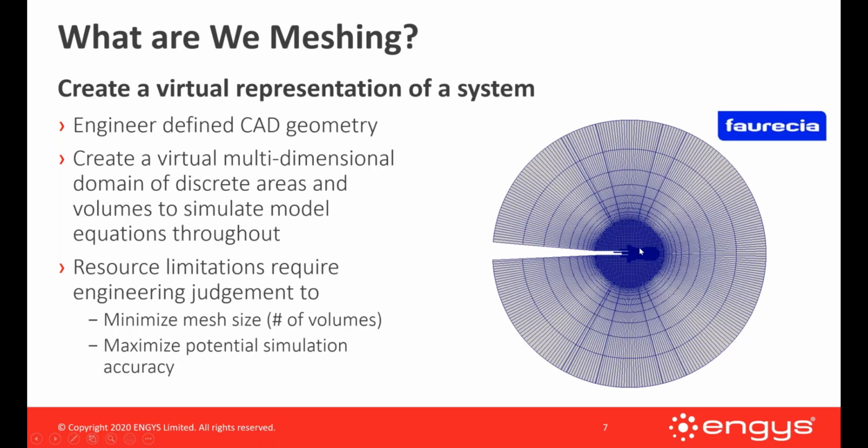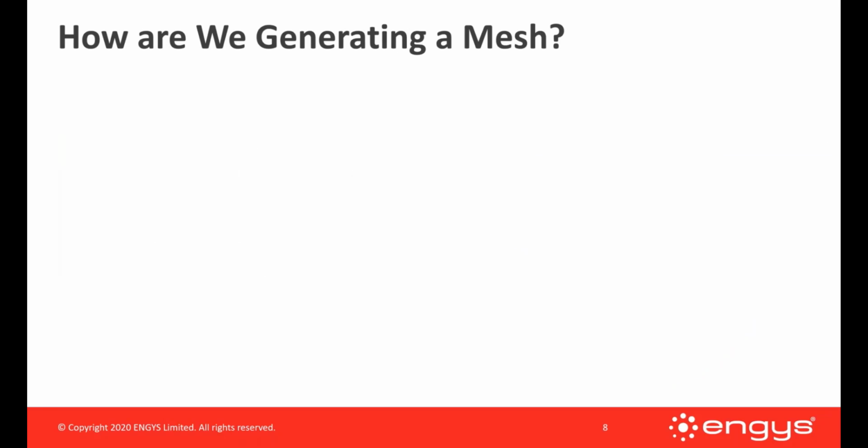And for this particular mesh, there's several different components. So near the muffler, there's extremely fine cells. Outside of that region, there's a little bit larger cells. Maybe we don't need to necessarily resolve those flow features a little bit more. And then outside of that region, we've got this ever increasing radially extruded mesh from this circular domain in order to capture these pressure waves far from the muffler so we don't get any reflection. Of course, we can have a boundary condition that prevents reflection, but this extruded domain also helps with that, capturing those pressure waves moving outward from that muffler.